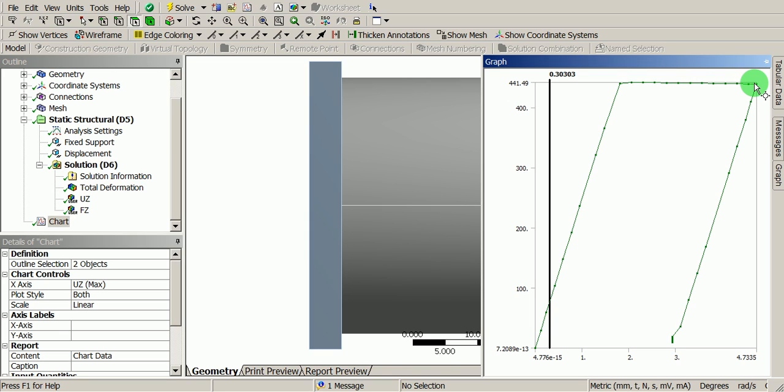When we started retrieving the platen back, the bush did not come back to its original state and it came back only 2 millimeters. The 3 millimeters of permanent set you can observe in this graph.